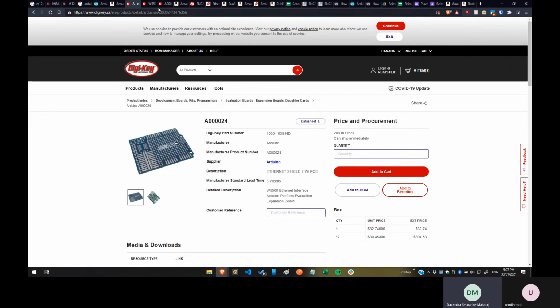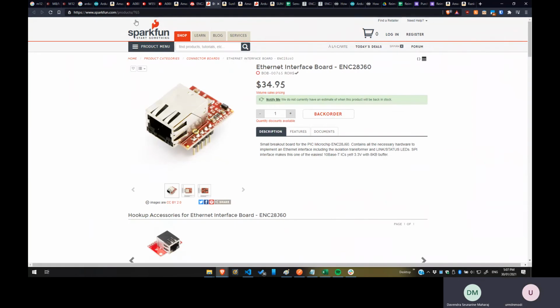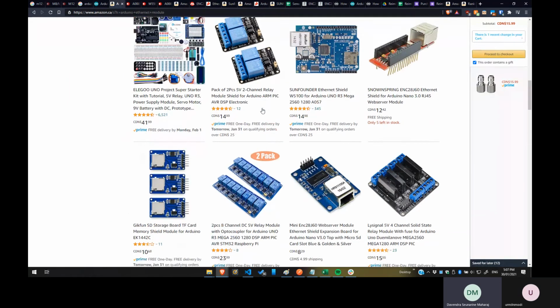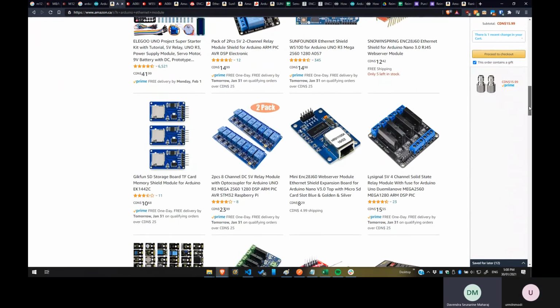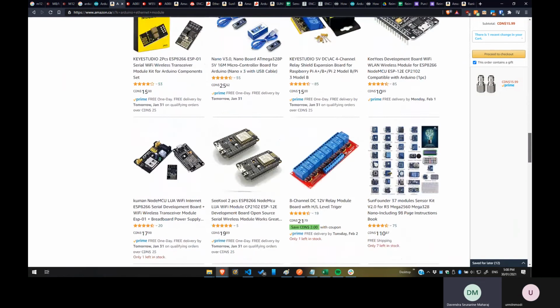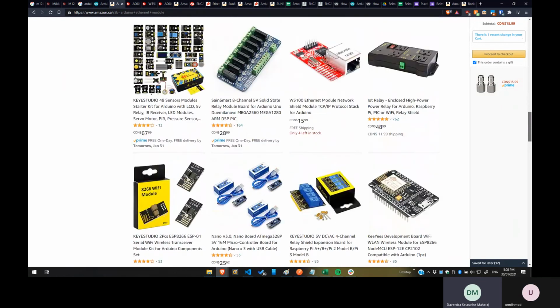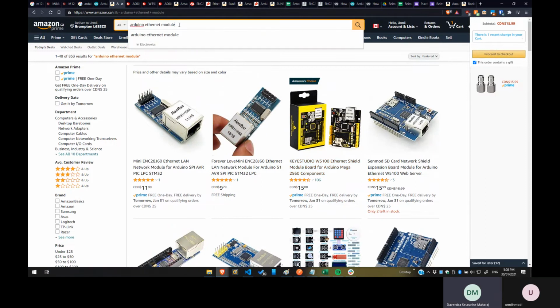So I tried to download onto it. The Odroid runs on Ubuntu or Android, so we're going to use Ubuntu for obvious reasons. I tried to download onto it, and then I realized that last year Matt never told us, or I don't know if you read about it, that you needed a micro SD card to download the OS image on it, and then you have to take the card and put it in the Odroid to load the operating system on the Odroid.